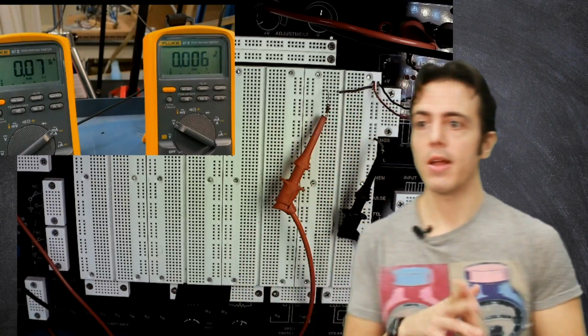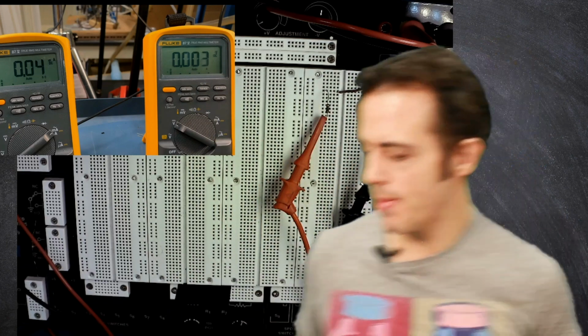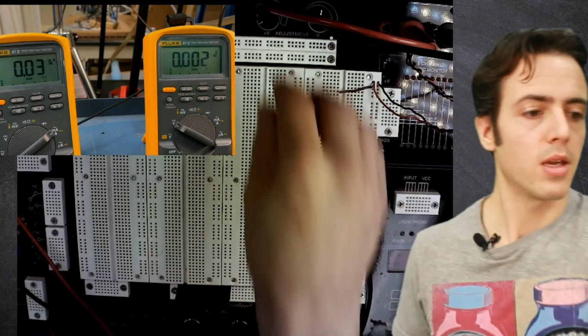So that's why we need to look at the power limitation of resistors, because it's important for our purposes to understand the maximum voltage that we can take them up to. So for those 2 resistors you guys have got, which is resistor 1 and resistor 2, you need to determine the maximum voltage we can take them up to. So I'm going to keep this circuit set up the same, and switch between those 2 resistors. I'm going to put a new resistor in, and I want to record a series of voltages, and then record a series of corresponding currents as well.